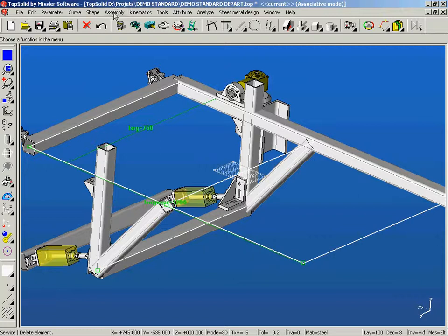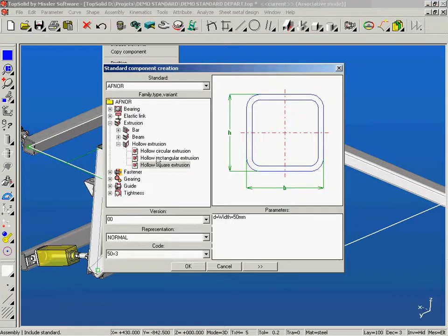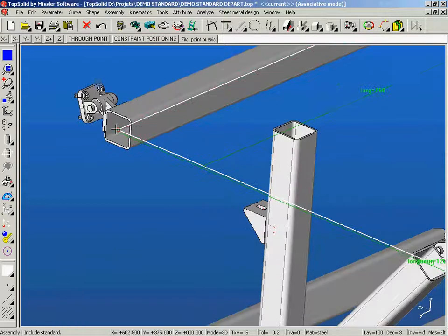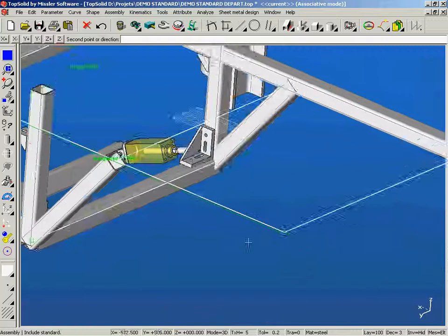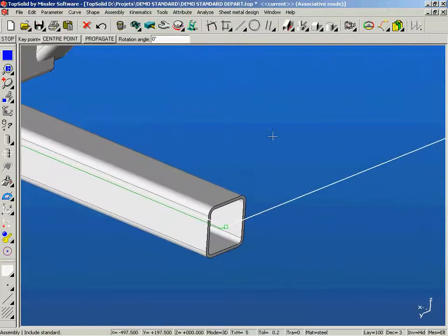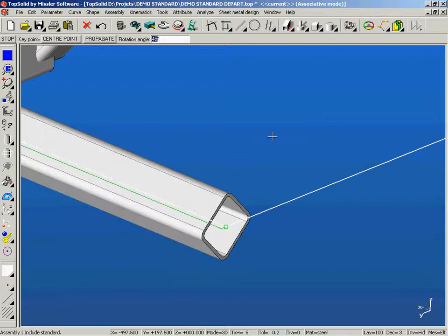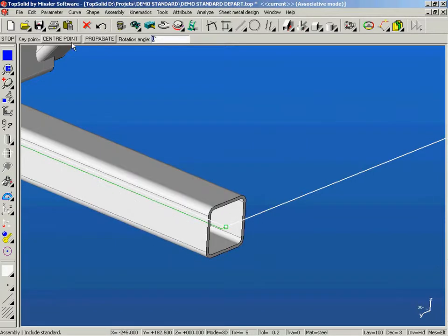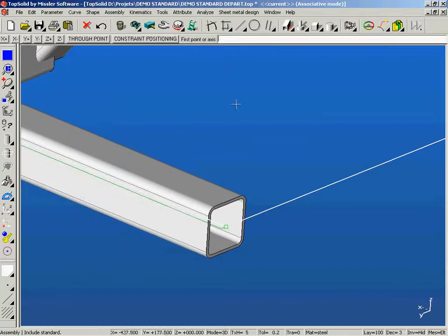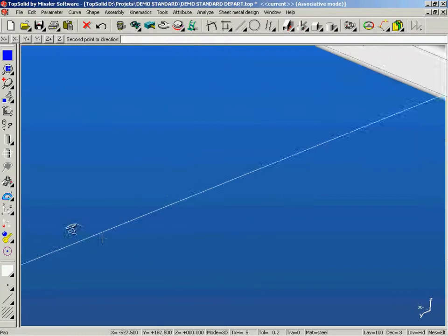TopSolid has exceptional functionalities for an in-situ design of a welded chassis. As a standard feature, we have a very rich library of sections of all types. We choose, for example, a square hollow section. We now position the components directly on the wireframe design drawing, choosing section justification.